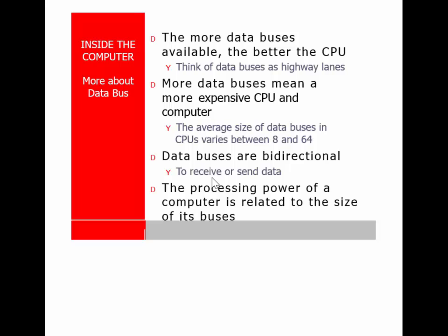Will an 8051, like the one at Pepsi, do it? I need more I/O; can I get that by going to a slightly bigger one? Do I need analog? Then I need to pick a device that's got analog I/O. If I need to be processing images and downloading files, well, I can't use a microcontroller. I'm going to have to go to a full-blown microprocessor. So you tend to have to look at the application.